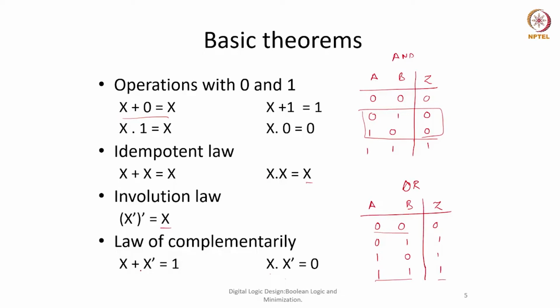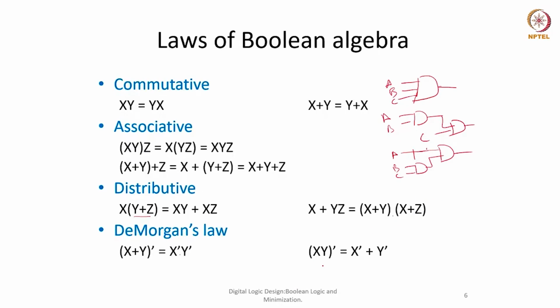Okay, here also, we have replaced this OR with the AND gate and 1 with 0, so it worked. This is how it was working. So we can see here also, wherever we were applying, we just need to replace. Here there was an AND gate, this AND was replaced with the OR, and this plus, meaning OR, was replaced with the AND. Then the expression x dot y will become x plus y, x dot z will become x plus z. So this duality principle says that the expression would remain the same, but we have to do it on both the sides.